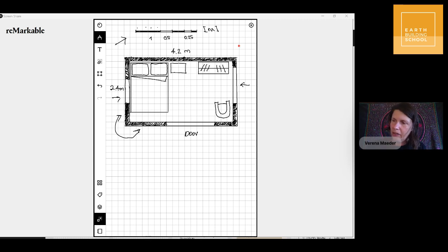Here, in this place here, there's definitely not enough bracing, and also having the window go behind your closet might not be so nice, aesthetically not so nice. So we're making this corner a little bit bigger too. In a very small building like this, you don't have that much playing space with your window openings on the shorter sides. But if the floor plan is different, if the room, for example, is square, it's different. So just check this out. So and this works.